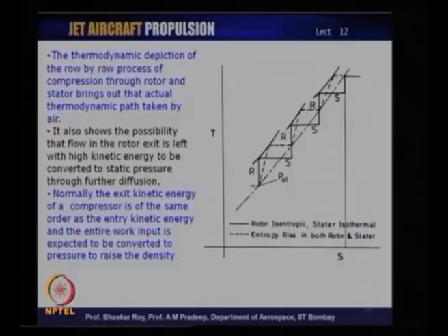If we look at the thermodynamic depiction of a row by row process of a compression through rotor and stator, we know the rotor does work and the stator does not do any work, really speaking. We will be talking about those things in great detail in the chapters to come. The thermodynamic path taken by the air through these compressors, through rotor and stator, can also be shown in terms